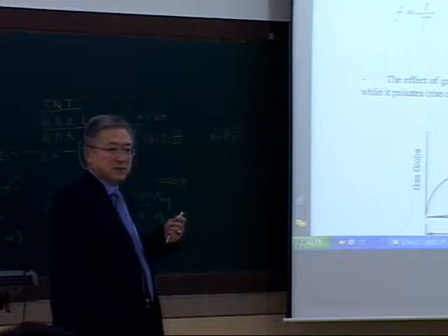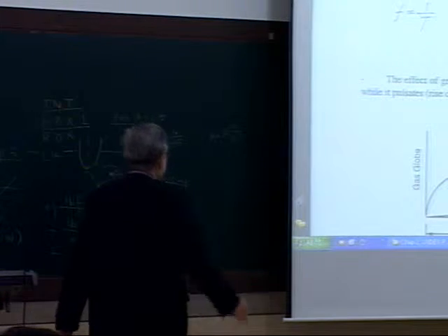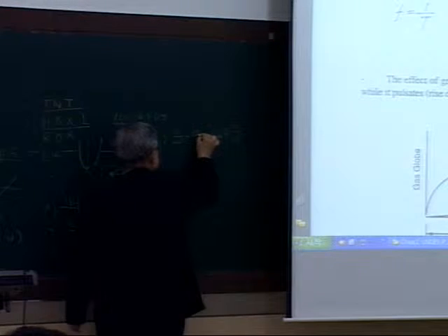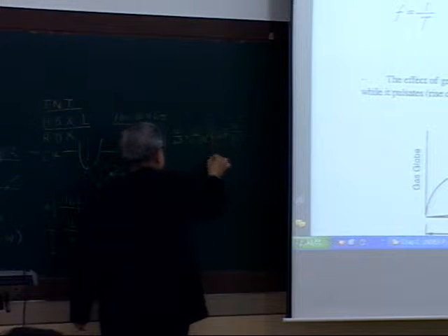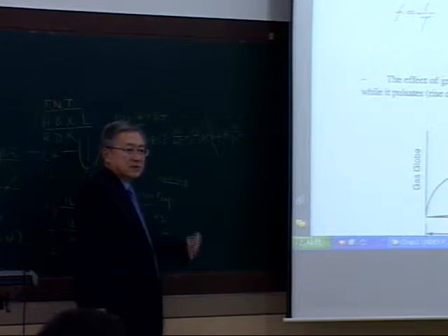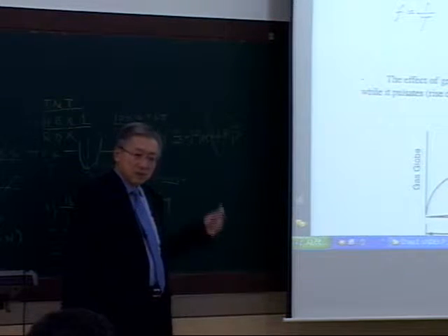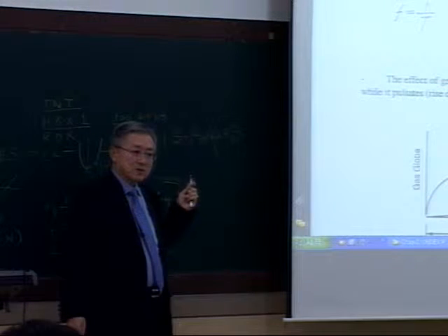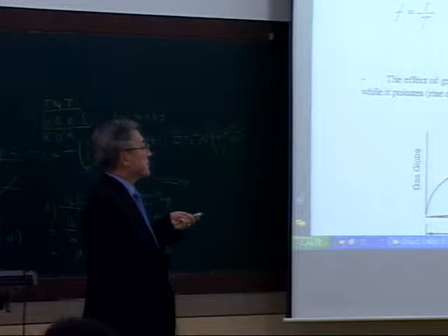All my notes are in pound, feet or inch and second. That's the reason I want to convert this inch to pound feet square, right? So what shall I do? Convert inch to feet. You have to multiply 12 inches, 1 foot, right? And square, 12 square, that's 144. That's where this 144 comes from.